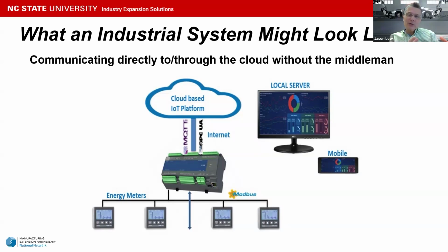So in our typical system, we might have that sitting inside of our piece of equipment. We might have the opportunity to have an energy meter on that piece of equipment, or I can purchase one and plug it into my PLC and talk to it that way, using a protocol, another protocol that you'll identify here, which is Modbus.